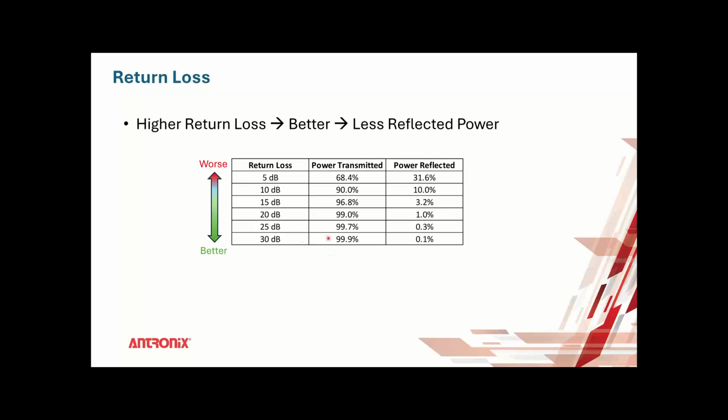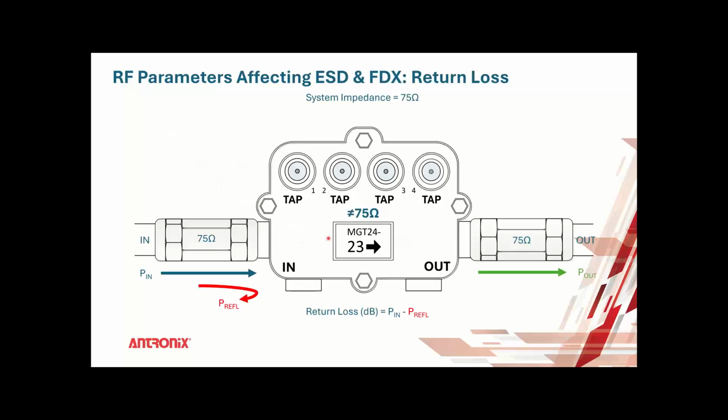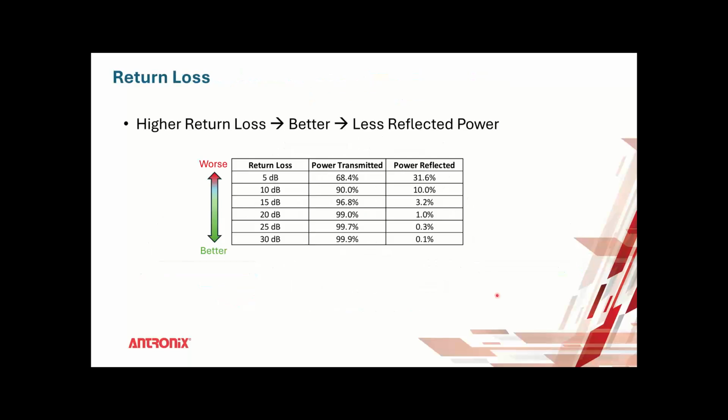On that slide, I have a question for the audience, if I may. So audience, if you pay attention to this, is a higher return loss a more desirable number, or lower return loss? So yes, higher return loss is a better number. So it means less reflection.